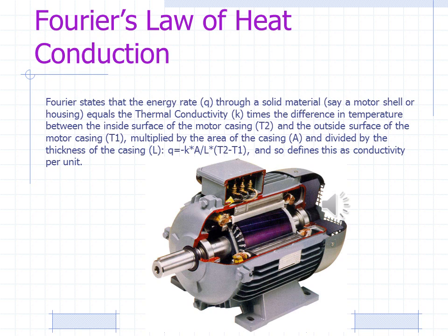Okay, Fourier's law of heat conduction. Look at the motor design and think about what's going on inside it and how you get heat from the inside to the outside. Realize that the purple rotor in this image has an air gap between it and the stators on the outside, and there are air gaps here and there. Fourier states that the energy rate through a solid material, say a rotor shell or a housing, equals the thermal conductivity times the difference in temperature between the inside surface of the motor casing and the outside surface of the motor casing, multiplied by the area of the casing and divided by the thickness of the casing.